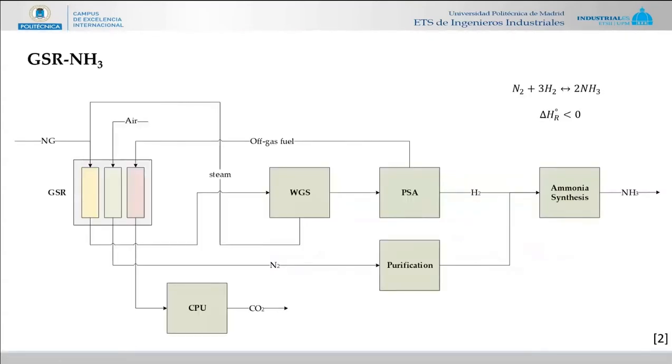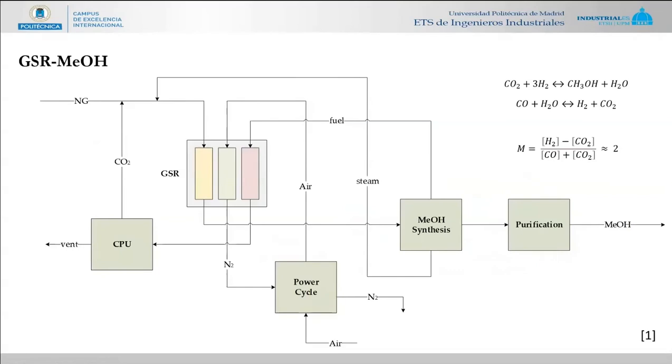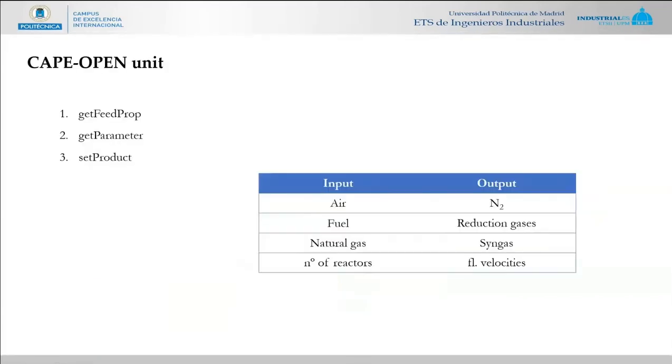It might look very easy on these block flow diagrams, but in order to comply with the energy balances of the gas switching reforming, it has taken quite some iterations, which would have been extremely tedious had it not been for the fact that the model output is immediately transferred to a process stream in the simulator.